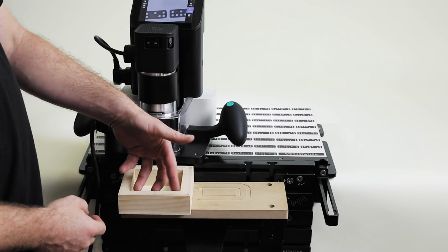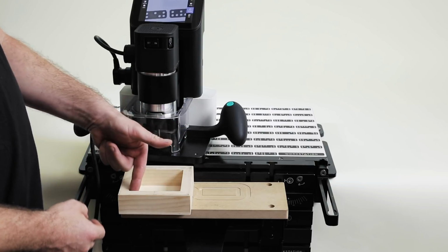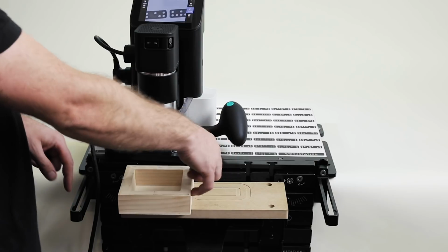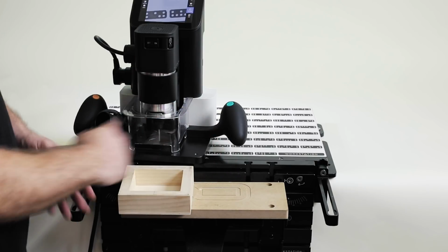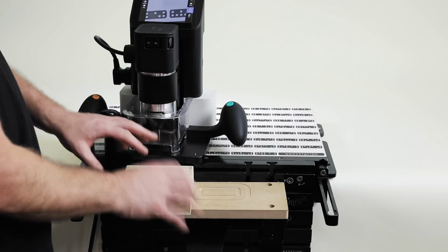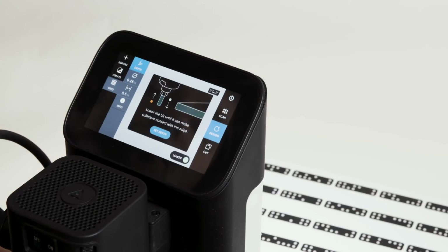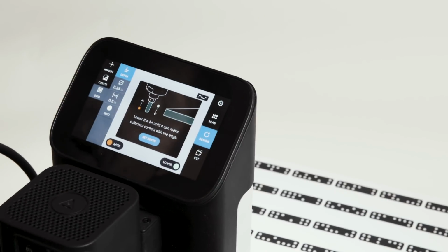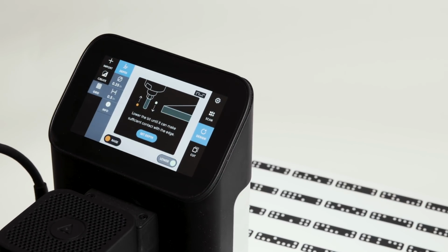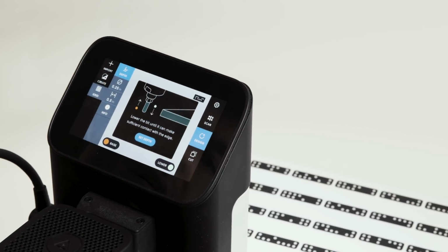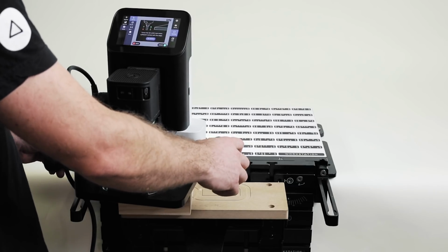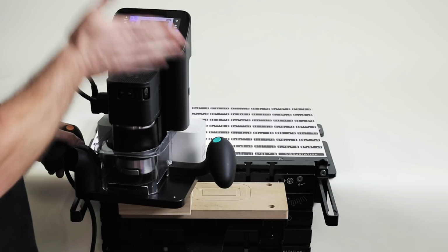Now we're going to look at a brand new approach where we can do things like start to probe the inside of this and then the outside and top. Basically any 90-degree element of stock we can now probe quickly and intuitively. You don't have to think too much about it. Grid, new grid. We'll leave the settings as is. I'm going to hover over the center, drop it down. Now ever so lightly touching it against the edge of my stock so that I don't introduce error.